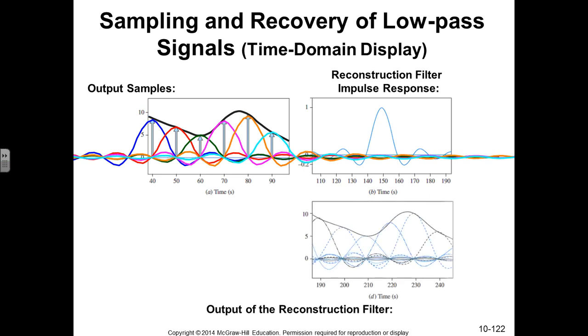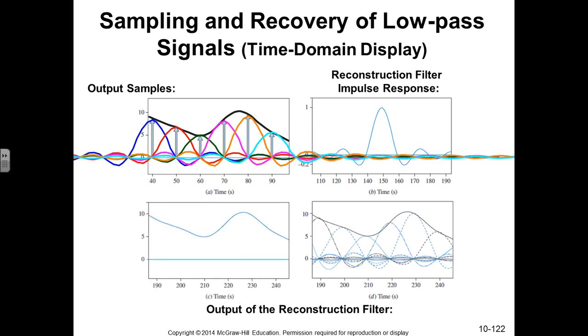And that sum of sinc signals would in fact give us an analog continuous version of our sample signal that matches the sample values at their instances and interpolates perfectly between them, giving the intermediate values that we need to make an analog signal. And so if we could create an ideal low-pass filter, it would be the perfect reconstruction filter. It would perfectly interpolate between the values of those samples to create an analog voltage that represents the one that we want from our output samples.